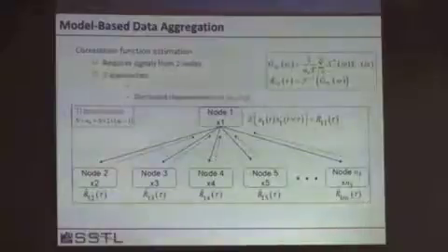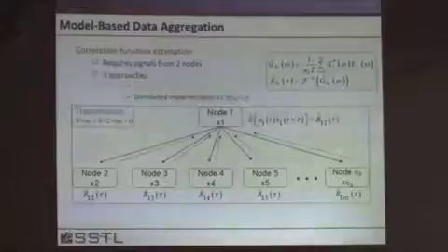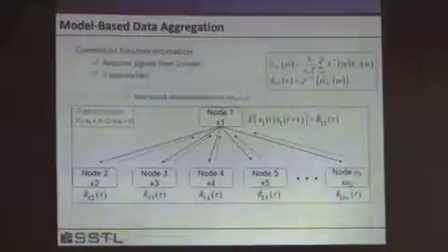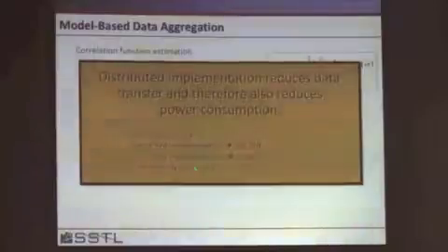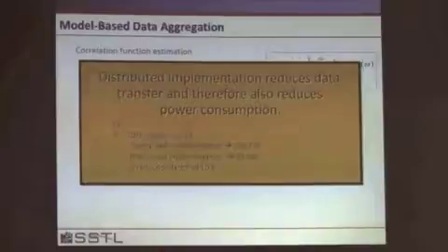What's the advantage there? How many data points in a typical cross-spectrum? 1,024, 512. I mean, you're doing FFT, so you're condensing the information down. Instead of having the raw data, you're condensing it down so you just have the power spectrum that you're dealing with. And the advantage there is that we can get about a 10-to-1 reduction in the amount of data that's transferred in the network, and as a result, you reduce the power consumption.